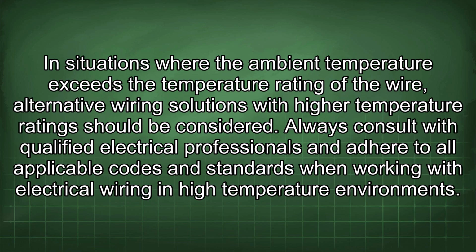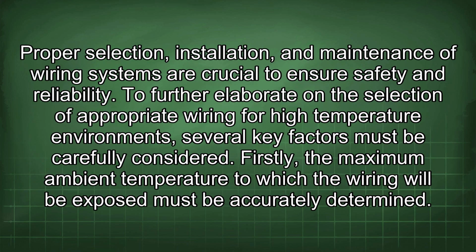In situations where the ambient temperature exceeds the temperature rating of the wire, alternative wiring solutions with higher temperature ratings should be considered. Always consult with qualified electrical professionals and adhere to all applicable codes and standards when working with electrical wiring in high-temperature environments. Proper selection, installation, and maintenance of wiring systems are crucial to ensure safety and reliability.